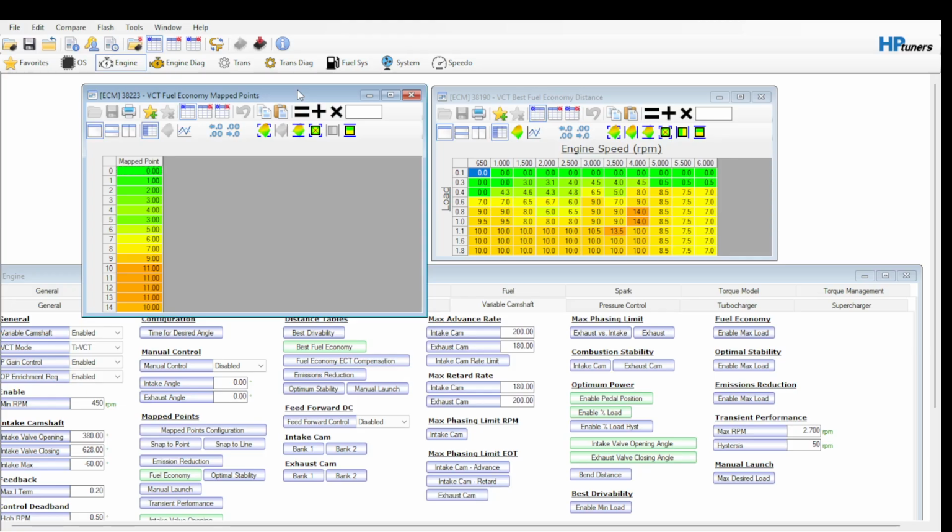I don't know if 3.5s have oil coming through the cams themselves. That I don't know for sure. I've not taken the head apart in a 3.5 liter. But my point being is that they use the oil pressure from the oil pump and the engine to act as a water wheel inside your cams with pressure, right? Not with flow. That's the important distinction.